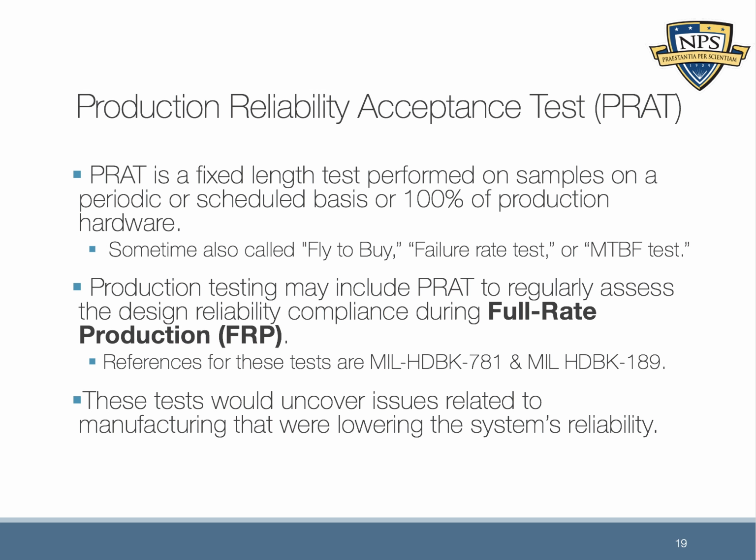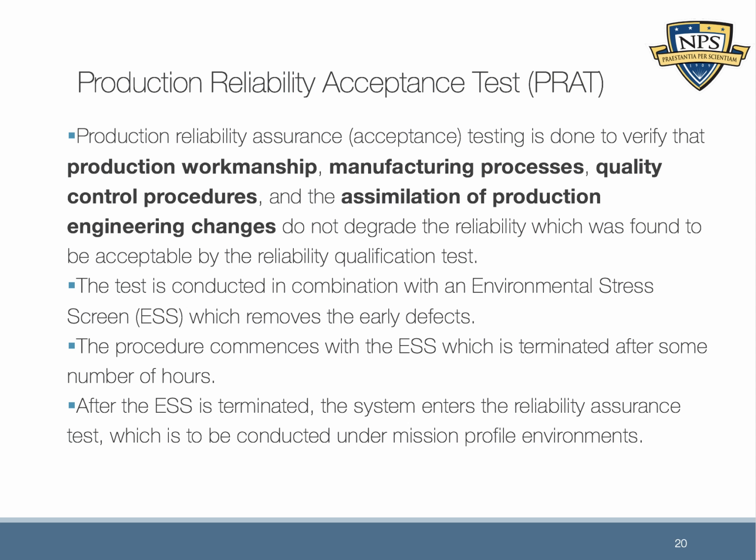It was actually caused by a dull saw. The electrical parts by the OEM were being cut, and the saw was old and dull, essentially pulling out parts of the part instead of cutting through it cleanly. So that's an interesting side story, but it's an example of something that might affect the reliability if not caught during production, and PRAT is designed for things like that.